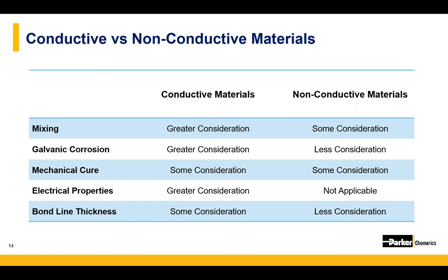I've said it before, it can be much easier to think ahead and design for a conductive sealant. And then if you don't need it, switch to the non-conductive, just because of some of the challenges in working with metallically filled materials. You know, I've had customers using a non-conductive adhesive with a very thin bond line, little real estate, that eventually fail their EMI test. And then all of a sudden they identify the need for a conductive adhesive. Now your problem is you have a 2/1000 gap and you're trying to dispense a minimum of 7/1000 thick adhesive. So it's not going to work out well, as you can probably guess.